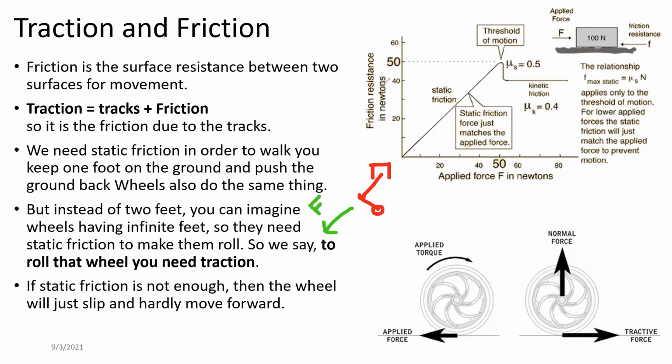If we use the piston again, the piston force from the combustion is acting downwards. A certain ratio of that force acts on the connecting rod, and that force rotates the crankshaft pin. The crank pin is rotated by that.